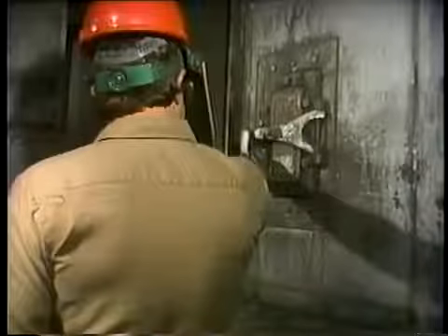Mirrors located just outside the control room may also be used to verify that a flame is or is not present in the boiler. Mirrors are usually aligned to allow an operator to see a reflection of the boiler flame through observation windows in the boiler. Of course, the most reliable indication of a boiler flame comes from opening an observation door and actually looking inside the furnace.